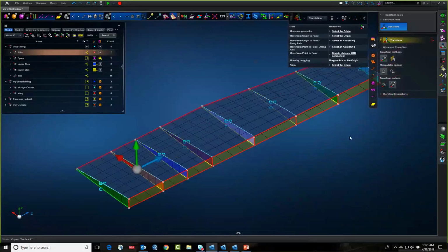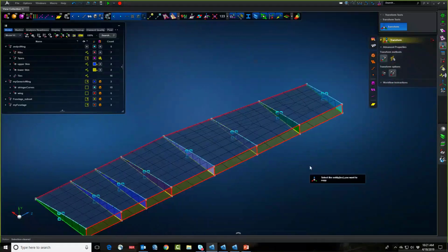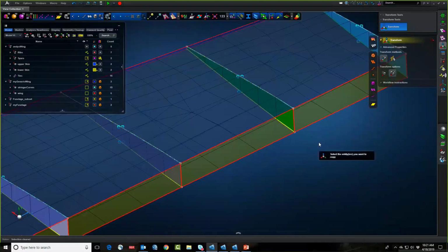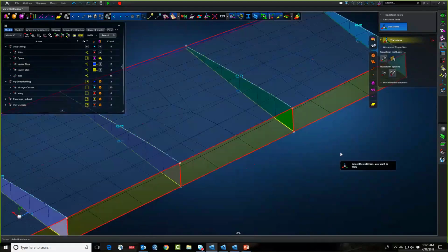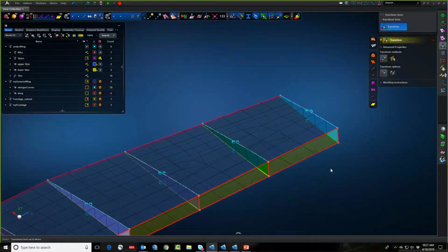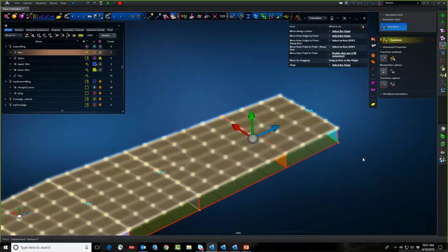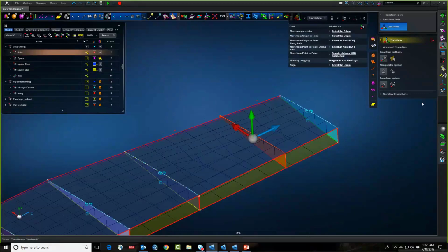And I know what you're thinking now. You're saying, okay, well, Larry, you did this on the easy part of the wing. What about this part of the wing out here where there's some changes in the orientation of things? It's probably not going to work quite as well there. And the answer is actually true, okay? So, just full disclosure. The reason is because the ties are applied with some kind of tolerance, right? So it is possible that you can move this guy and he's no longer in tolerance, which means I've now broken the tie. Not a big deal in Apex though.